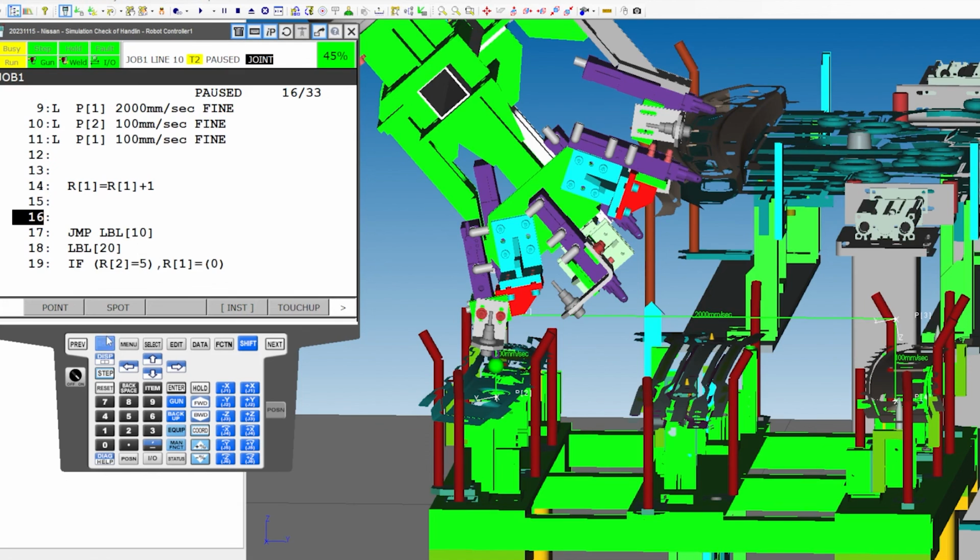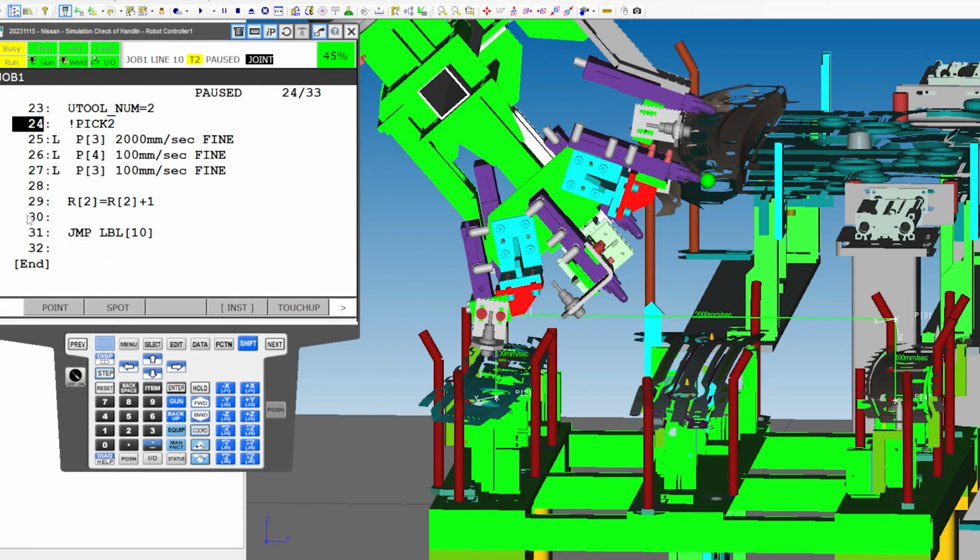Actually, one other thing I think we can check here is in Roboguide, shift coordinate 2. So see how I just shifted that to 2? See how that dot changed? So I go shift coordinate, I'll type in 3. Notice how the dot just changed over there? So I actually want to use 3 on this pick 2 because I feel like it'll just work out a little better. It may not work out better, but that's what we actually used in this actual program.